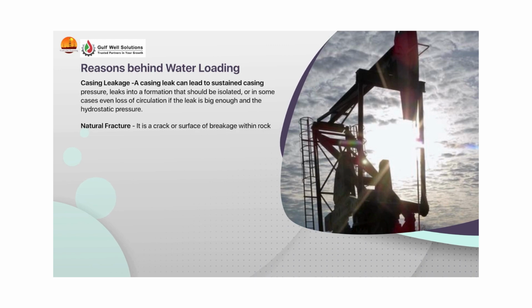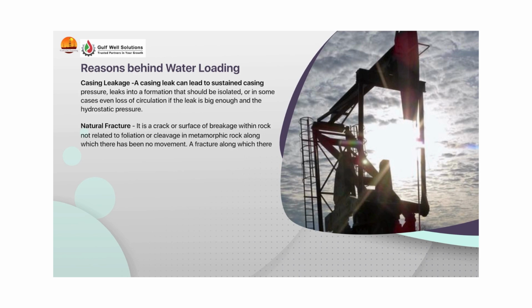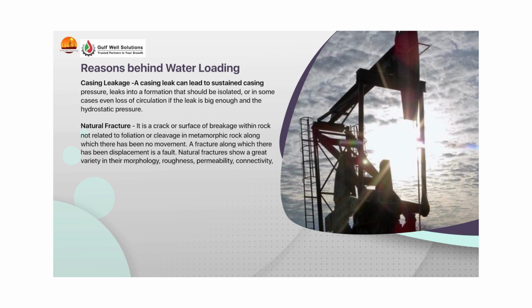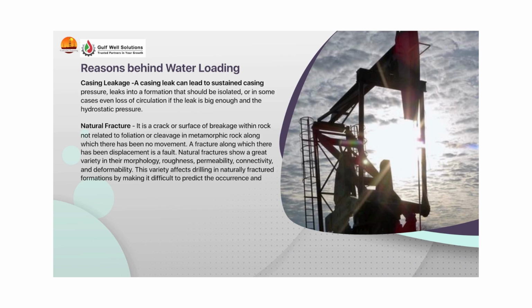Natural fracture is a crack or surface of breakage within rock not related to foliation or cleavage in metamorphic rock along which there has been no movement. A fracture along which there has been displacement is a fault. Natural fractures show a great variety in their morphology, roughness, permeability, connectivity, and deformability. This variety affects drilling in naturally fractured formations by making it difficult to predict the occurrence and severity of mud losses.